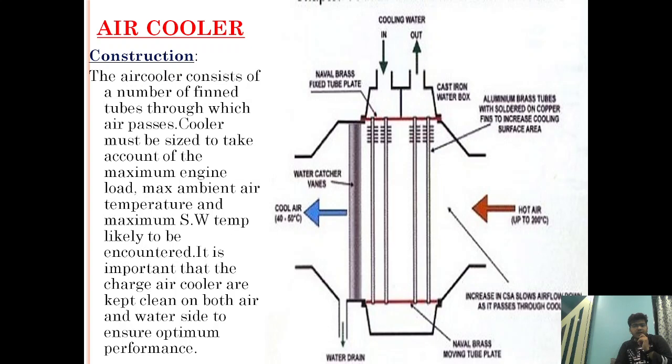Why are fins provided? Fins are provided so that we are increasing the overall surface area of contact of the air that is flowing through the air cooler. By the number of fins, we are increasing the surface area. As the surface area is increased, the contact with the cooler is increased and the air is cooled in a very short period of time.